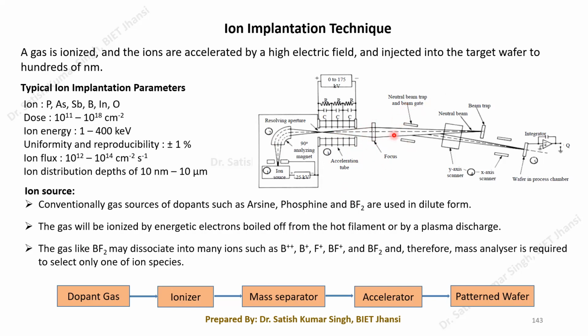Basically, after this, there may be a chance during the travel of these ion beams that an ion may take one electron from its neighboring ions, and then it will become neutral. Once it becomes neutral, a neutral boron atom traveling cannot be controlled by electrostatic potentials.